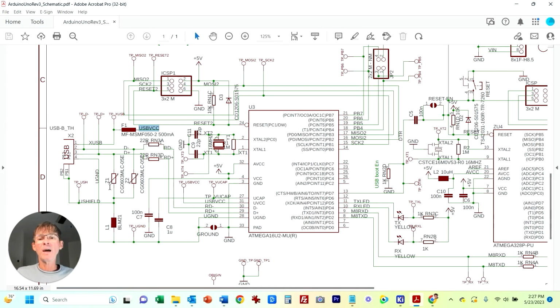But then we also have these 2 devices here, Z1 and Z2, which are for ESD protection of the data lines. And I'll pull up the data sheet and show you the details on those in a moment. Then we have L1, a ferrite bead, and this bead is just to stop high frequency noise injection. Then we just have some decoupling capacitors on our VCC.